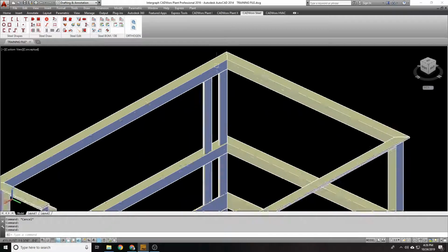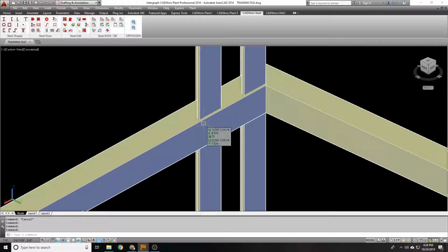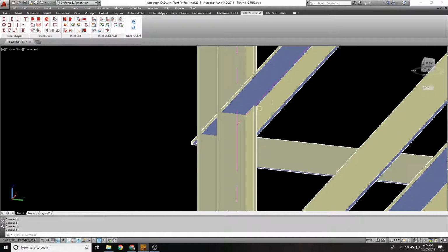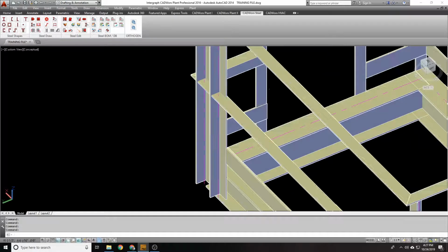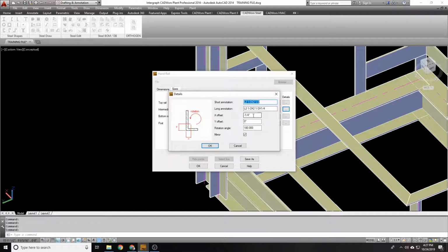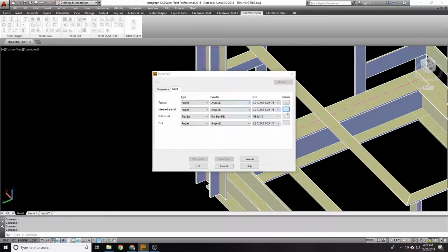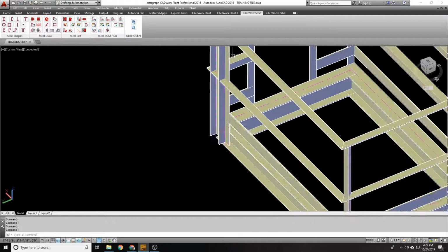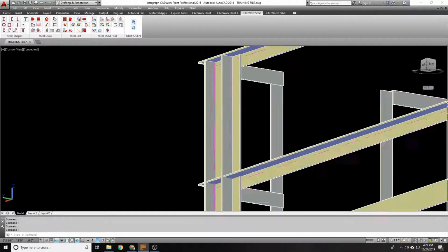You'll also notice that the top and mid rail come out 1/4 of an inch, which is great, because that's kind of how it would be. You would have this on top of your post. So the thickness is 1/4 inch. You'd have it on top of the post. There's that 1/4 inch thickness. In order to get that to work, the profile has a 1/4 inch offset. So you take a look at your top and your intermediate rail, and you've got this 1/4 inch offset in the X direction, which you can see is right here. We've offset it minus 1/4 of an inch, and it pulls it out that 1/4 of an inch. Same thing here, except we're also doing it 1/4 inch in the Y axis because we're trying to put the top post on top.